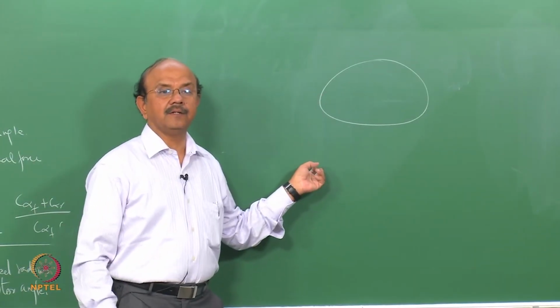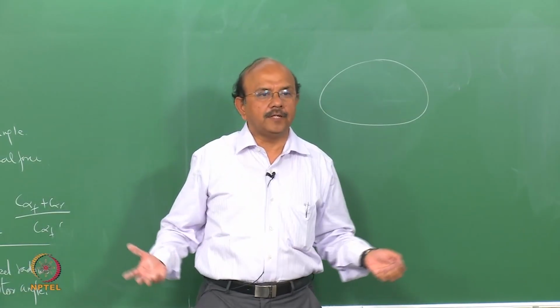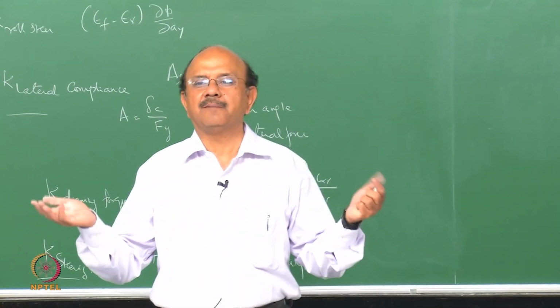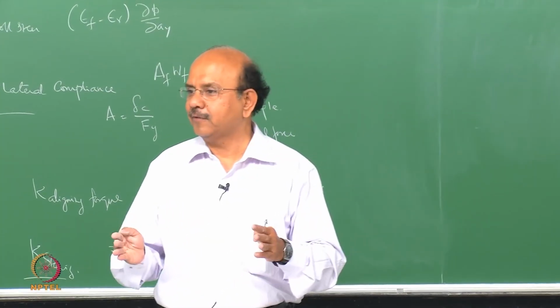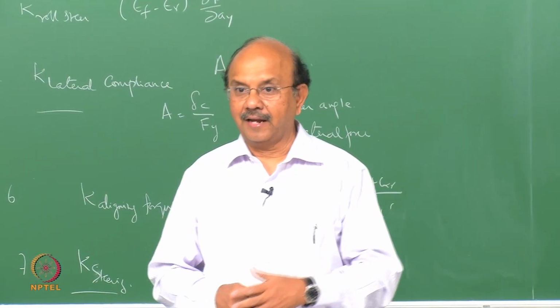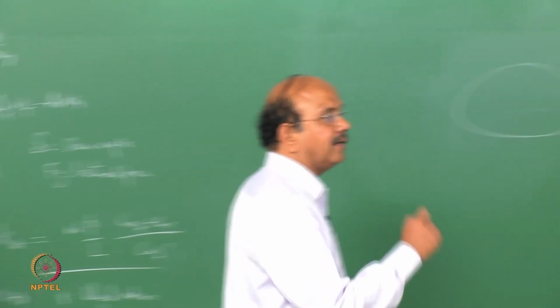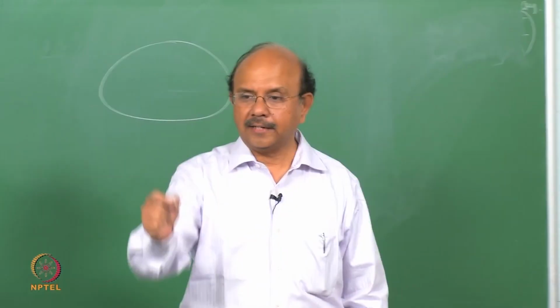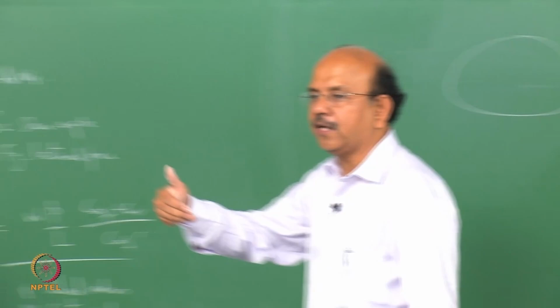So they have a questionnaire. In fact, questionnaire design is important, and there are standards now. You can't go and ask, obviously, you're all students, hey, how was the car? Did it go well? No, man, it's a damn squib. This kind of thing won't work. You have to have a proper questionnaire and a proper test procedure. So you have to say that I am doing steady state cornering on a smooth road. Are you able to hold the line? This kind of thing. In fact, Krolla and others have got into about 39 questions.